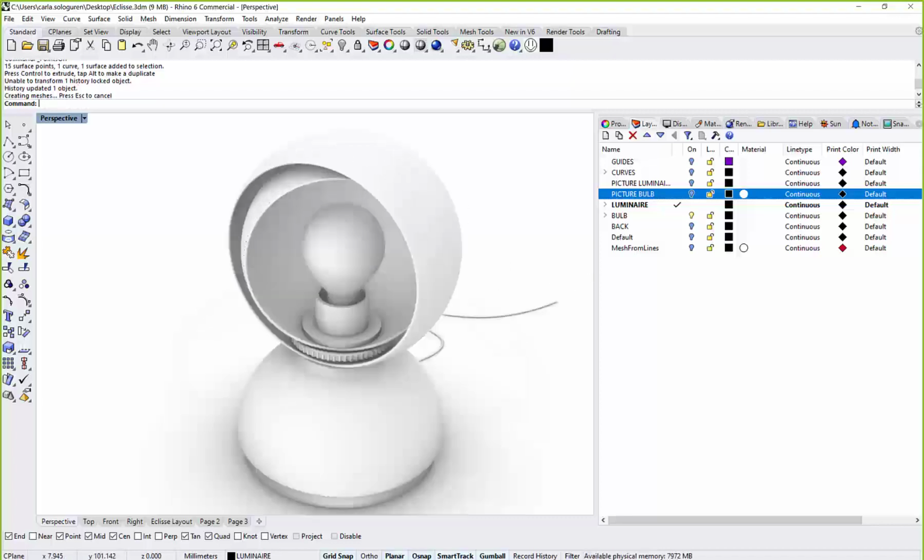Actually, record history has been there for a long time, but it's like the basic foundation of Grasshopper. So if you're running any command, revolve, loft, and you really want to remember all these points for further editing, what you need to do is mark this. It should be selected, and it should be light blue. This has nothing to do with working in Grasshopper, it's just for Rhino.